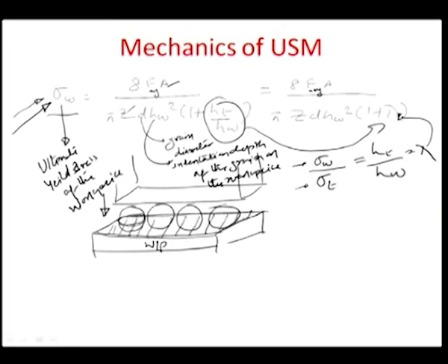So if we assume that the number of grains acting, let us say these are Z numbers in one impact between the tool and the workpiece, is inversely proportional to the square of the diameter of these grains, which also signifies the area of projection of one grain, it will not really be improper to assume this kind of a relationship.